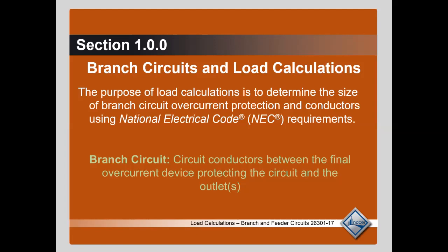Now, when we're dealing with appliances, we have to do a couple things. One, we have to actually look at the nameplate rating on it, and it's going to tell us what the ampacity of that breaker is. And let's say, for example, it said that breaker must be no larger than a 25 amp breaker. Okay, if I go with a 25 amp breaker, there's a good chance I need to run a number 10 wire to it. Okay, because I can't use a number 12 wire,